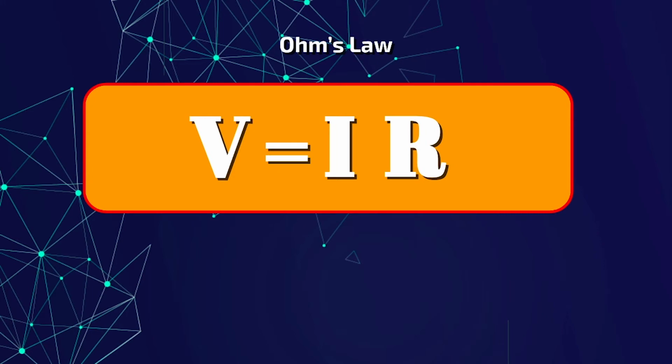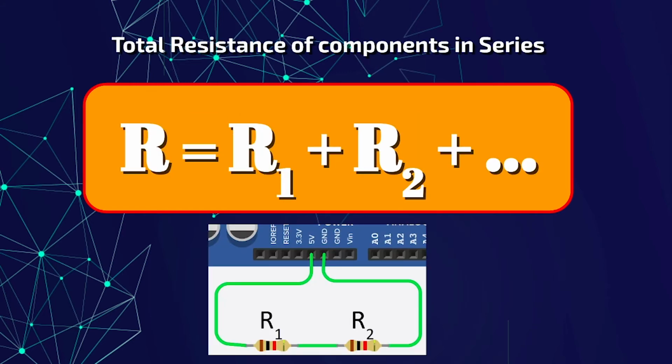To solve our problem, we're going to need the help of Ohm's Law. V equals IR. The voltage is proportional to the product of the current and the resistance. As our circuit has the voltage fixed, in order to decrease the current in our circuit, we would have to increase the total resistance. To do this, we could connect a resistor in series, as the total resistance of components in series is just the sum of all their resistance.